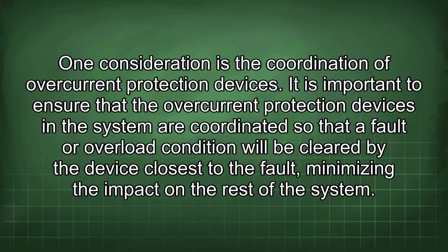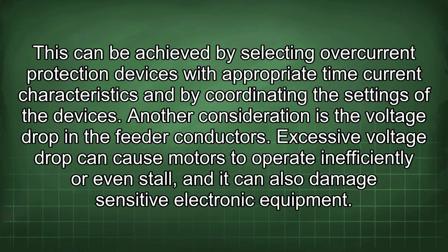One consideration is the coordination of overcurrent protection devices. It is important to ensure that the overcurrent protection devices in the system are coordinated so that a fault or overload condition will be cleared by the device closest to the fault, minimizing the impact on the rest of the system. This can be achieved by selecting overcurrent protection devices with appropriate time current characteristics and by coordinating the settings